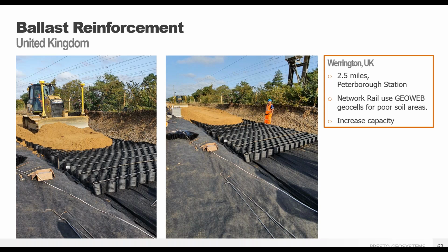The aim of this project was really to increase capacity for passenger trains. So it involved building a couple new tracks tunneled under an existing line. This line opened in late 2021 and really did remove constraints caused by freight trains, which always seem to slow everything down, right? This one included the 6-inch geocells to increase track stiffness. You can see here that the contractor really wanted a precise installation, so they used stretcher frames on this project to keep the panels open.